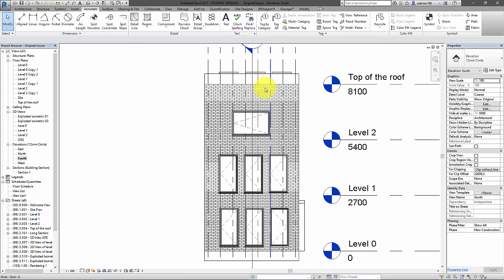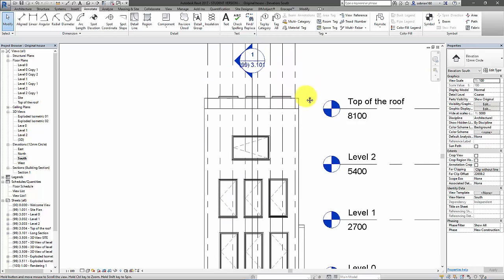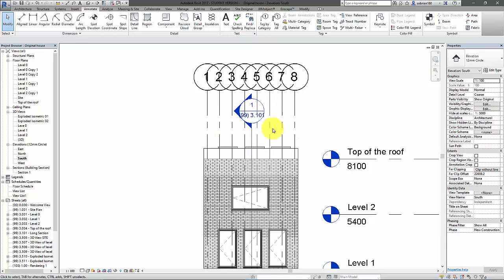Take the grids away, or at least loosen them up a little bit, make them gray or something like that. You don't need all these 600mm grids. We only did that in the first semester, just so that people really got the idea of the 600mm. But wherever the structural walls are is where you put the grid lines. You don't need grids every 600mm anymore.